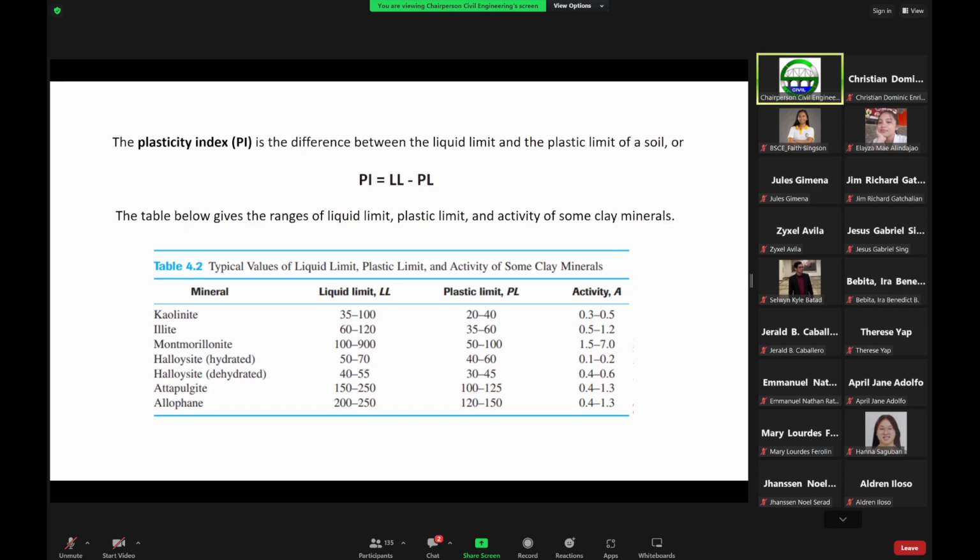These are usually the collapsible soils, the expansive or swelling soils, and also the liquefiable soils due to earthquake. In the geotechnical reports that I normally prepare, I always specify this: for your particular site, we have found some collapsible soils, or some expansive soils, or some liquefiable soils.